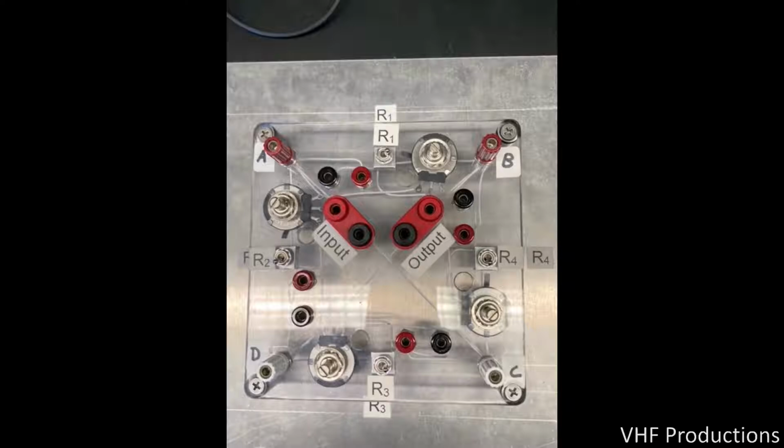We can then input a connector between the black and red connectors, such as a strain gauge. And when the switch is switched all the way to the left, the strain gauge itself becomes the resistor R1 in the path between pins A and B.